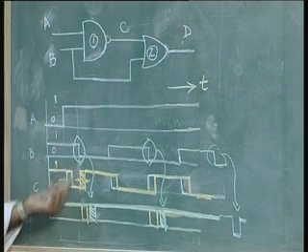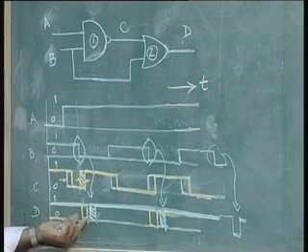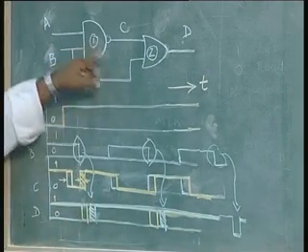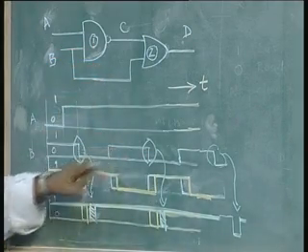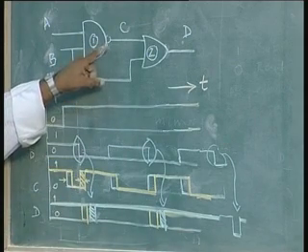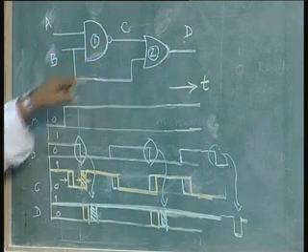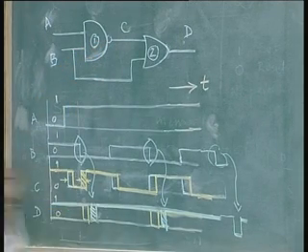So, clock is high, even though the clock is high, the D does not remain 1 all the time. Of course, D is 0 in this case. I will have to do some inversion, one of these gates has been inverted. This is only a concept. So, I have to invert one of these gates, maybe this NAND gate can be an AND gate. If you make one of these inversions, this becomes a positive pulse instead of a negative pulse.